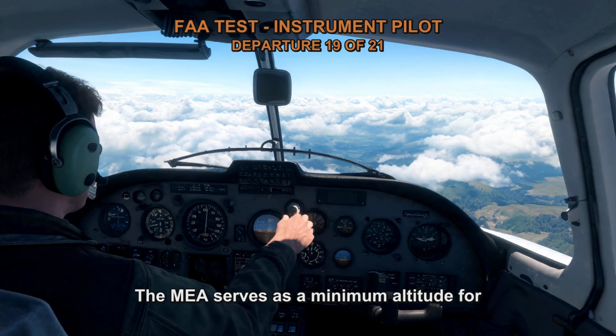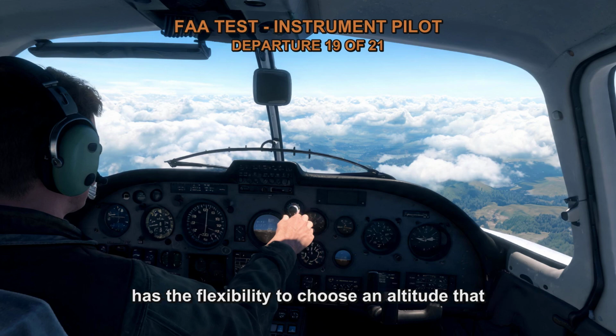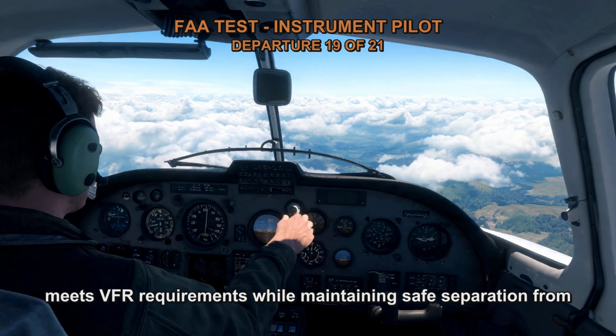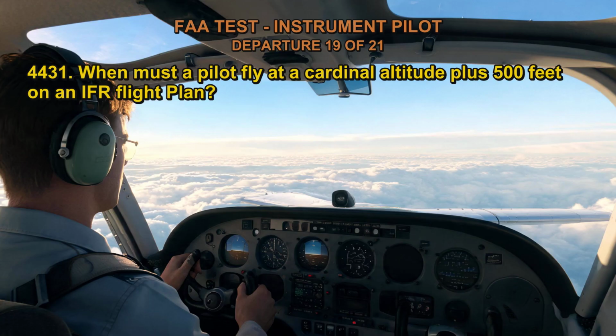The MEA serves as a minimum altitude for IFR operations, and when operating VFR on top, the pilot has the flexibility to choose an altitude that meets VFR requirements while maintaining safe separation from other aircraft and obstacles.